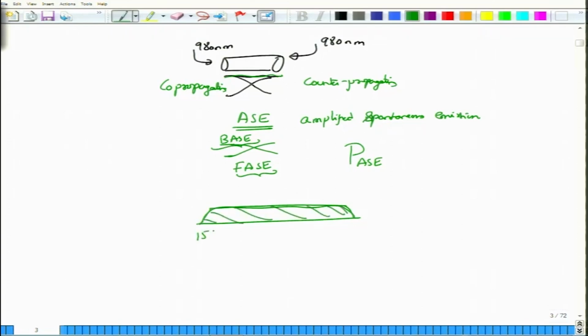It can cover all the way from 1500 to about 1560 nanometer, which is the range we are normally interested in. Of course, you do not really use the entire range for a given channel. Each channel will have a certain band, as we have talked about in the previous module. Over that band, if the bandwidth is say B0, the total noise power present in this band is given by